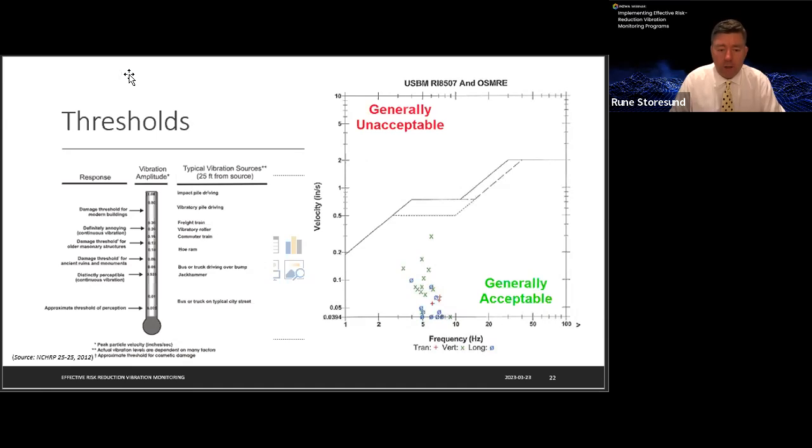Well, for all of these calculations, I'm going to encourage that you do some site-specific sanity checking and cross-checking. I would suspect that there is going to be a relationship between the vibrations and whether the device is installed in the ground or on the structure. You just need to establish what that soil structure interaction looks like and what effect it has on the propagation of the vibration. So you'd want to do some site-specific checking, but you could absolutely have devices on structures in the ground.